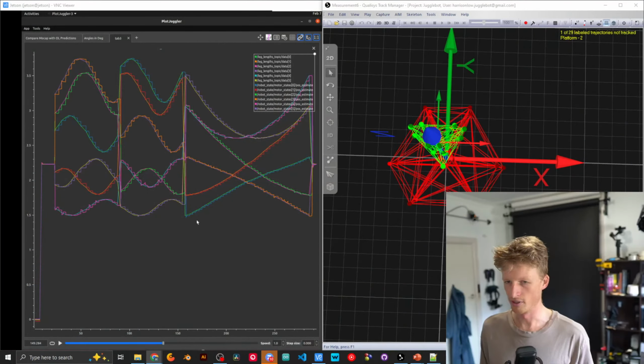James is saying the top would be skewed if one leg were off from the other in the bot itself. If you can identify a compensation, you could tune the bot to accommodate the different base offset. Yes, that's exactly right. If you can identify a compensation, you can tune the bot to accommodate the different base offset. That's the goal. So yeah, the plan here is to have the robot...